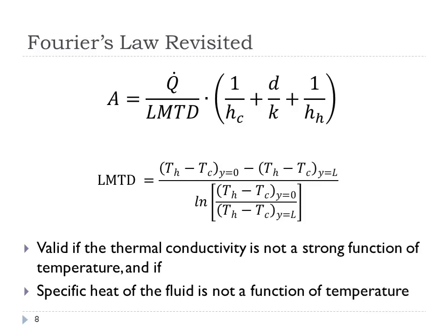We have the resistance for heat to flow from the temperature in the center of the hot side of the heat exchanger to the wall separating the hot from the cold side. Right? If this is a gas or liquid, heat has to transfer from the center to the wall. It's got to go through the wall, so that's resistor number 2. And then from the wall, it's got to transfer to the cold side gas or liquid. So that's what we have here, 3 resistors in series.